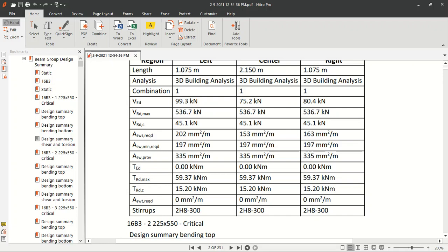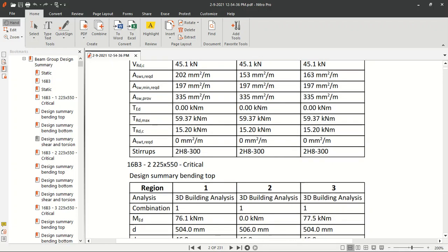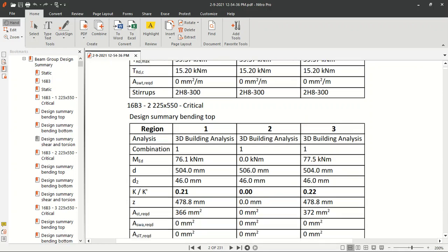the shear provided. So here you can see the reinforcement detail for the shear. The maximum shear this member can take is this. This is the maximum shear for this member. So the calculated shear is this, so we are good to go. So we just provide this because definitely we need shear links. But in terms of shear, the member is good. So that's it. So you now move on to the next member.